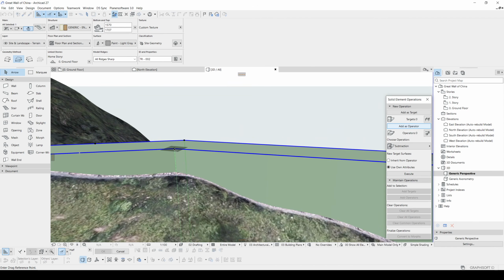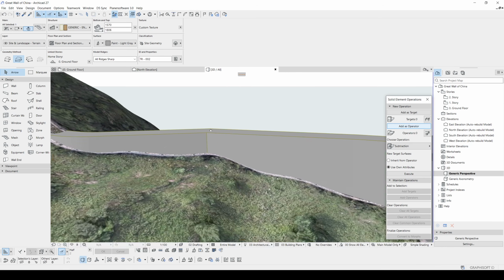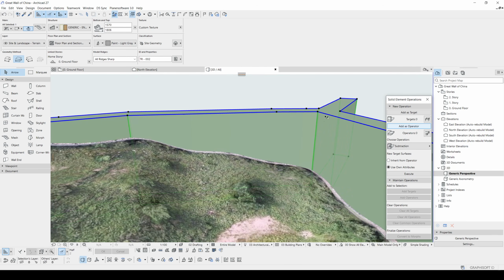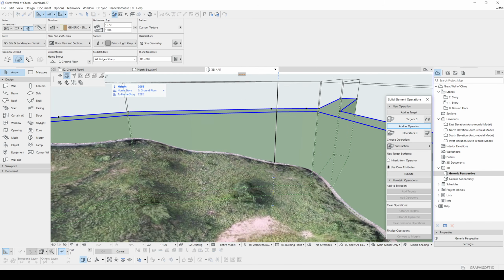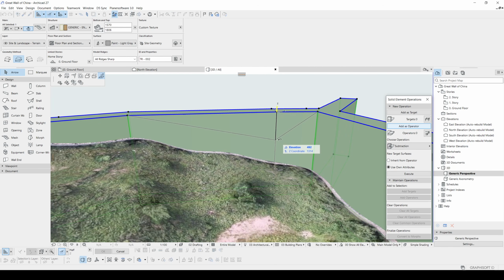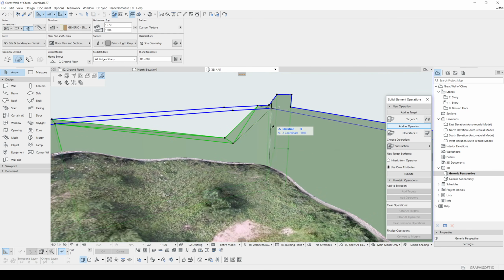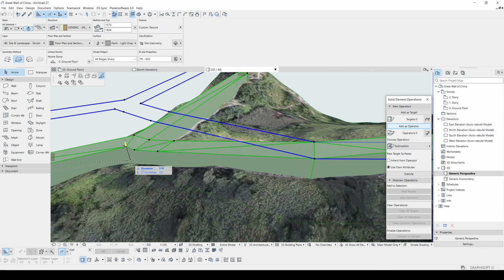First I will move this point to ground and then change the distance to 350. After that we will click the points one by one and adjust their levels with the eyeball. Of course you can do more precise. With this icon you can elevate your points. You can just move your point to the ground, hit the minus and input 350. You can just snap your points with your other points as well. By doing so, your model will be precise.